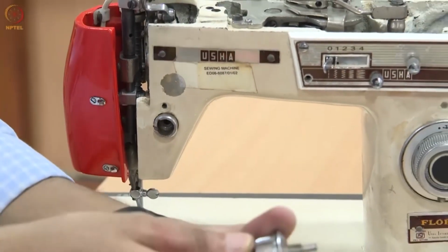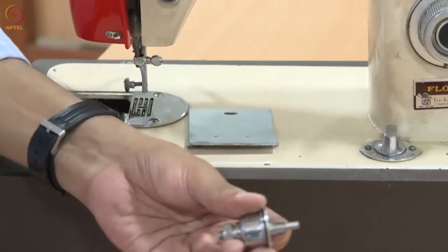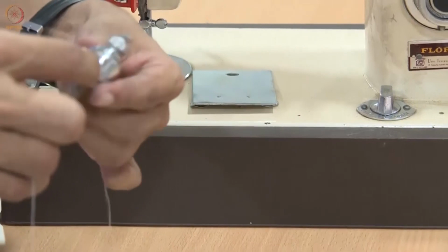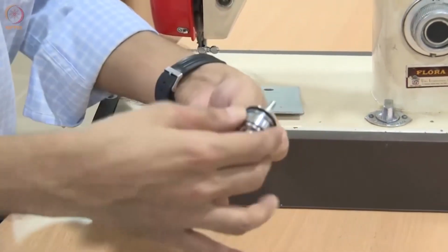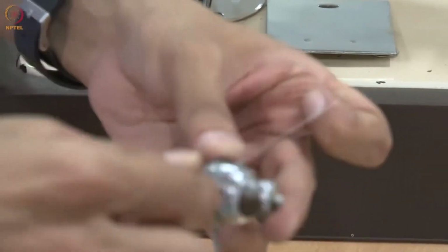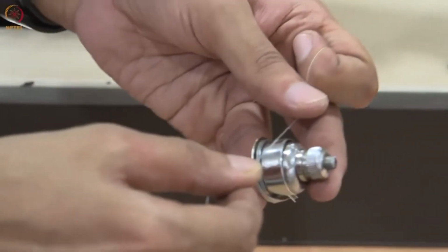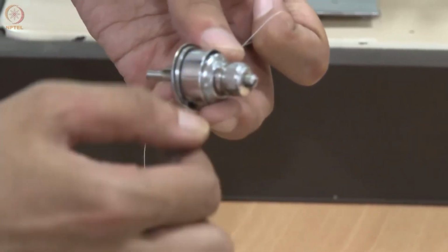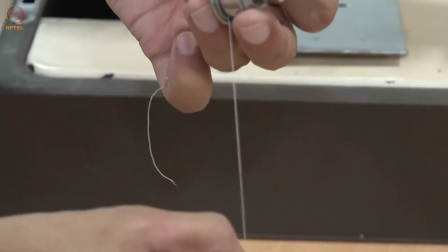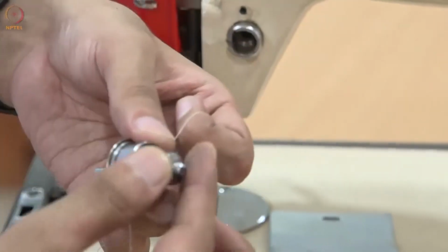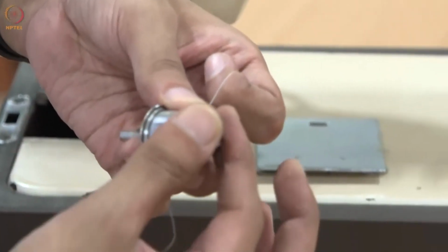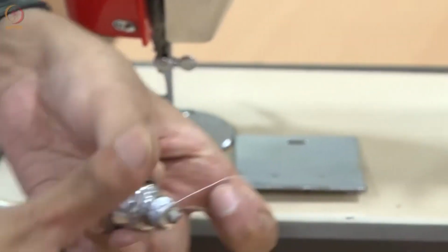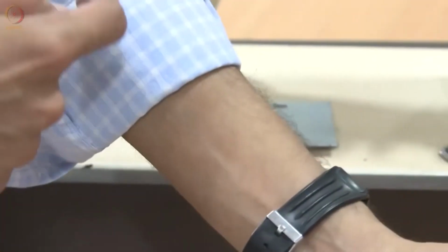So you can see here, the thread gets wedged between these two plates here, right? So this is how it is wedged. As the thread gets wedged, when I tighten this, it increases the clamping force, which means it will basically increase the tension on the thread. If you put too much tightening force here, the thread basically will break. If it is too little, again there will be slack and the stitching will be too loose.